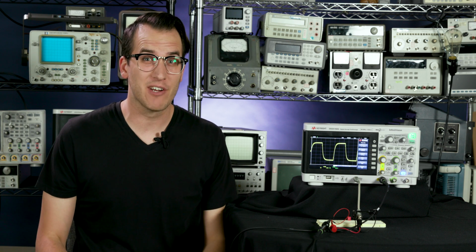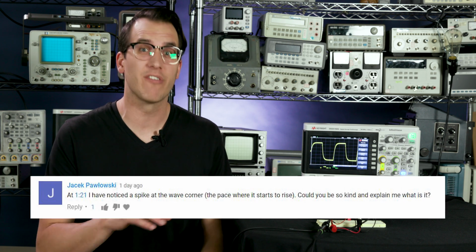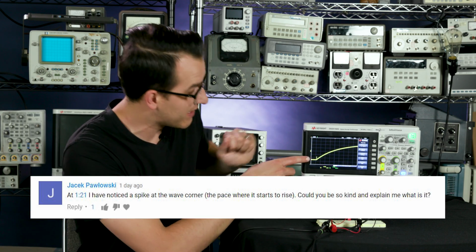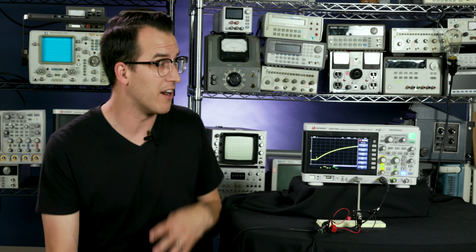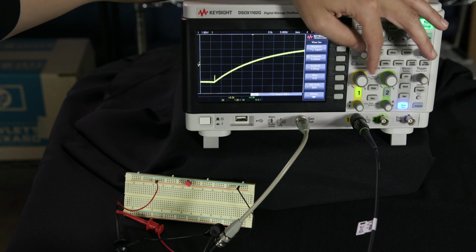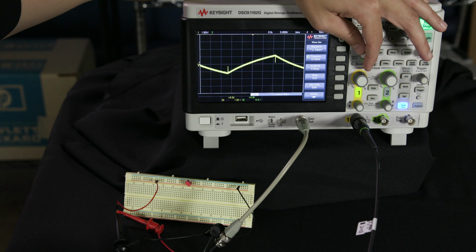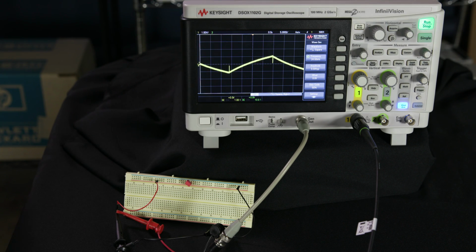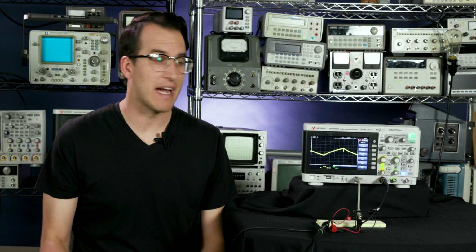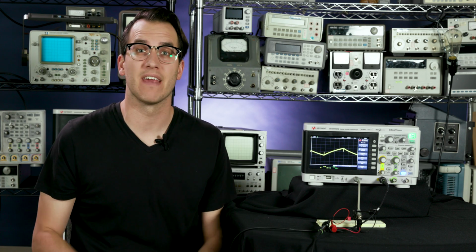In my last 2-minute Guru episode, somebody with a sharp eye noticed a little glitch on the waveform, and if we zoom in using that same circuit, we definitely see there is a little bit of a glitch there, and it actually makes itself more prevalent at higher frequencies. So if I crank that up, we can see that there's a glitch both on the rising edge and the falling edge of this simple capacitive circuit. And we were able to narrow this down to some simple parasitic inductance in my circuit.